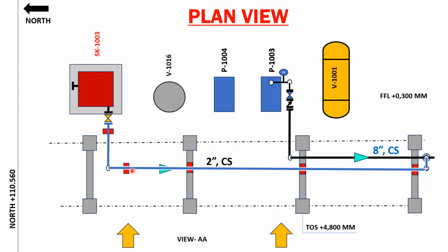Okay, so I'm going to provide a support over here for the safer side. This is going to be a rest support. So basically how many supports have we provided? 1, 2, 3, 4, 5. The first 4 supports we placed comfortably in order to ensure the line is safe, and the 5th support we have placed in order to ensure that there is no sagging after further evaluation.